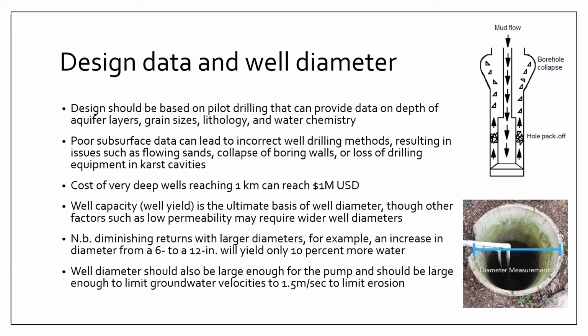So other technologies or methods should be considered when you are looking to increase the water yield in a site. Okay, in some situations, you might have to actually establish a well field or use multiple wells to increase the yield of your groundwater project.